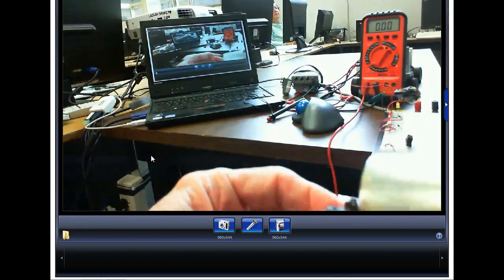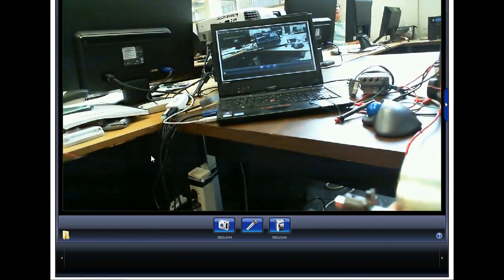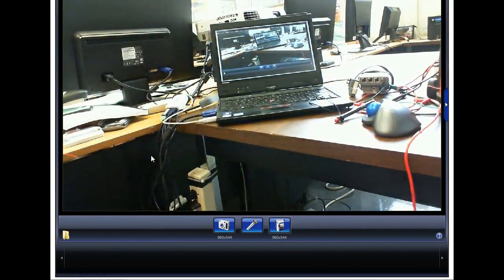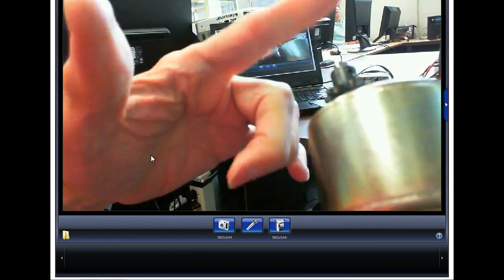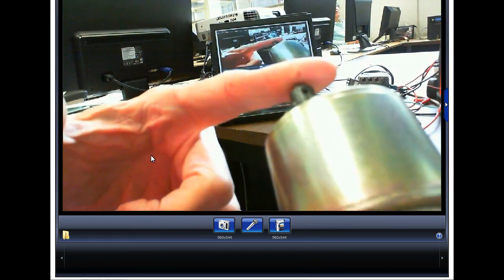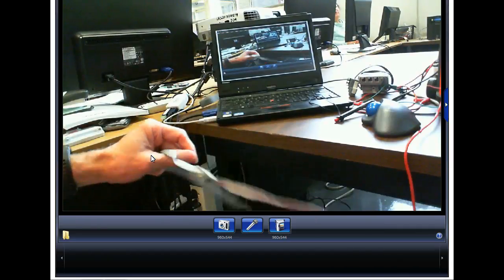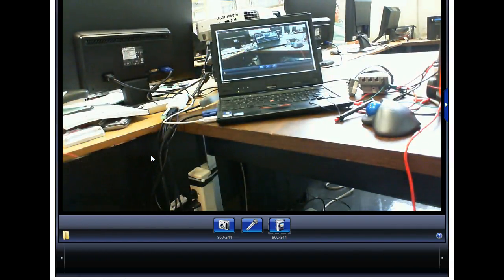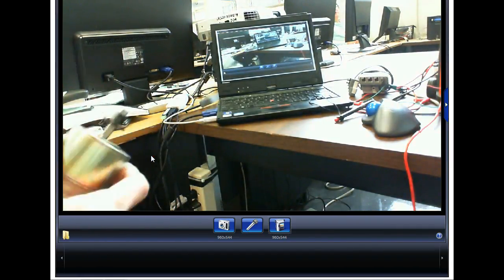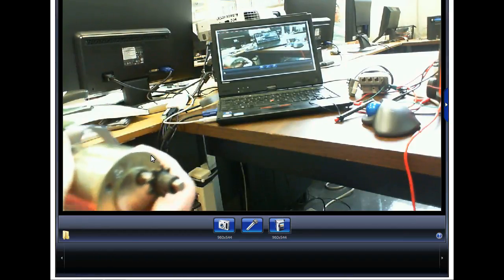So it looks like this has very poor resolution, but like we said, for every 1 revolution back here, I'm back here turning the motor. I don't know if y'all can see the thing turning or not, but it is. So I'd have to turn this 65.5 times for this guy right here to make 1 turn. So to get the resolution, we'd multiply the number of slots times 65.5, and that's how accurate this robot was, which is nothing compared to the encoders on this robot back here.